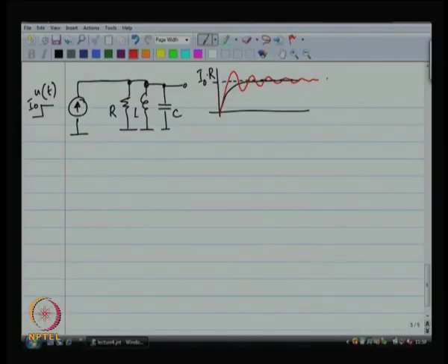Typically if you observe this waveform on an oscilloscope, you can just look at it and estimate the Q of your circuit. So, all you have to do is count the number of cycles you can see. So, over here I have drawn 1, 2, 3, 4, 5, 6 crests and troughs. So, I can estimate, and off the back of my head I can say that most probably this network has a quality factor of 6.